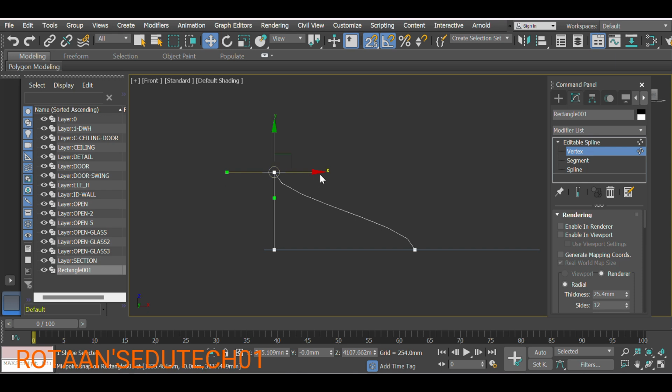That's why we have to create corners. Select, then right click and Corner. Now if we make this surface or this corner near to it, it cannot be disturbed. It can easily come near to this wall.